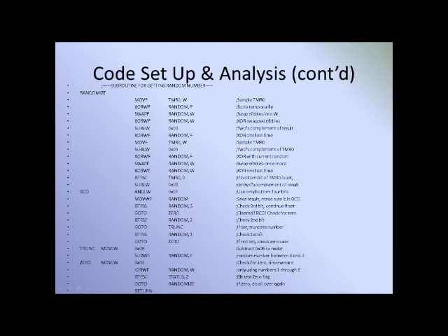Through a series of swap instructions, more XORs, and taking the 2's complements of some results, a second sampling of timer 0 and a final bit test of timer 0, a new value was acquired. This new value, stored in random, was generally above the range of numbers needed, which for the 3x3 keypad matrix were the numbers 1 through 9. So, the program made sure to mask everything except for the bottom 4 bits by ANDing the new value with hex 0f. This limited the range from 0 to f.